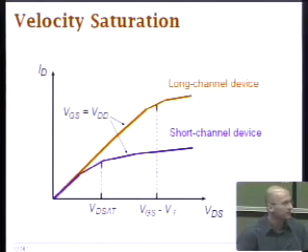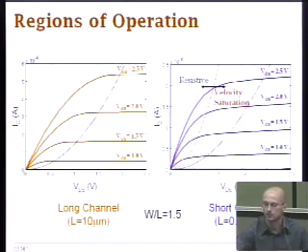Other... capacitance. That's very good, yes. So we'll see that in the performance analysis, just to make sure that you understand this, is that in performance analysis we will see that capacitance, due to the increase in area, also increases substantially, so that effect is actually dominant in the long channel device. You still end up with a better performance from your short channel.